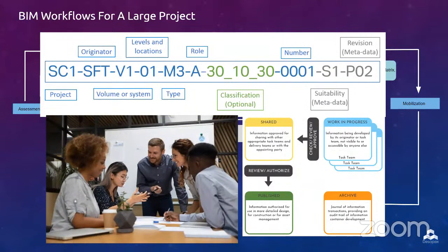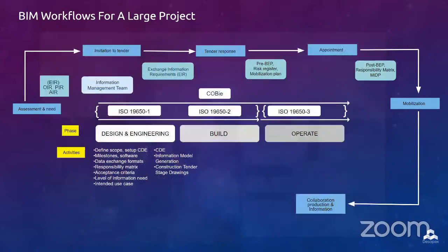Weekly virtual design reviews, or the VDRs, or in general we call them coordination meetings, will be organized to track the project progress, manage the critical constructability issues, and design changes that may be required by the owners. The coordination issues with other design consultants will also be managed based on the tolerance and coordination guidelines set by the owner. Any change that is made in the design revision will also be documented and processed as per the change management system set out in the BIM execution plan and the EIR.